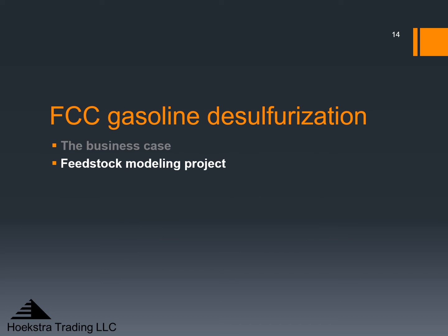Now the rest of my time will be on a specific project we did for a refinery on feedstock modeling for gasoline desulfurization. This refinery wisely wanted to be able to model and optimize the feed to its gasoline desulfurizer because they knew the performance curve depends strongly on the detailed composition of the feed, and that is a high leverage point for their refining margin.